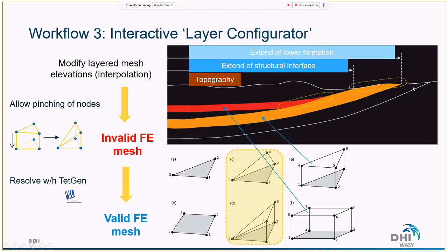In FEFLOW we have layers and slices. Slices are two surfaces which define a layer, which is a volume. So you can say your topography is slice 1, and the bottom of the model is slice N. Fix this, and then you add additional slices to build this layer in yellow. Because you have fixed or classified the layers as non-movable before, these new slices are actually intersecting here, and FEFLOW will connect them automatically.